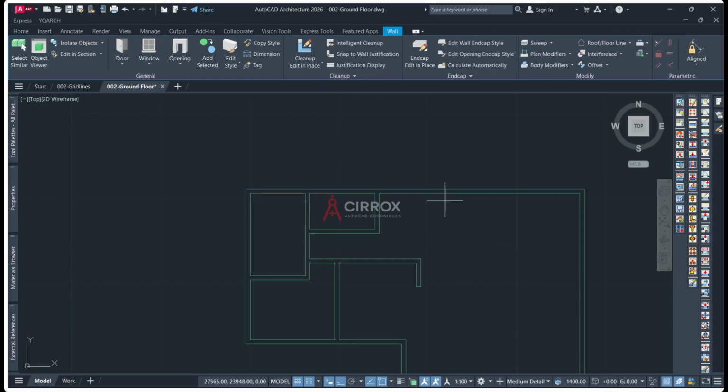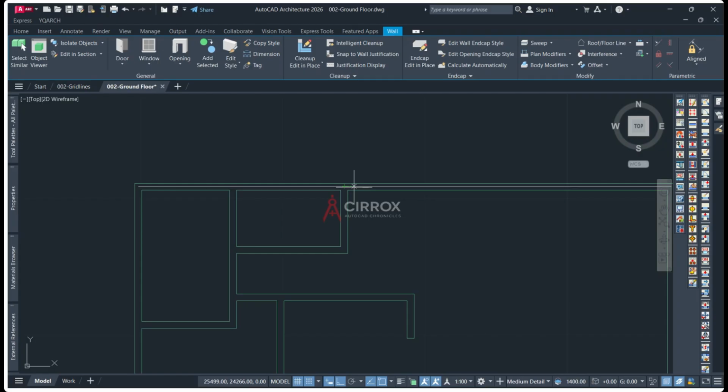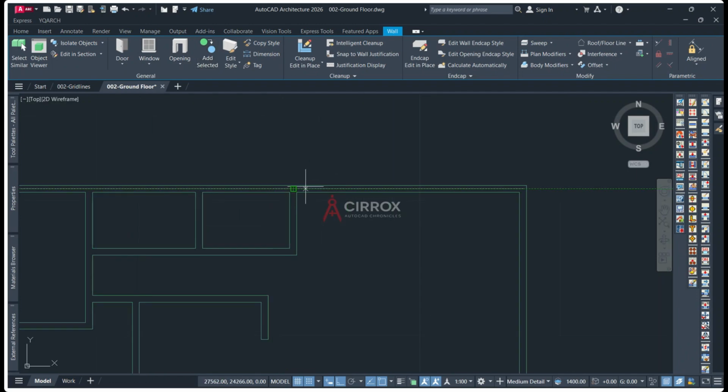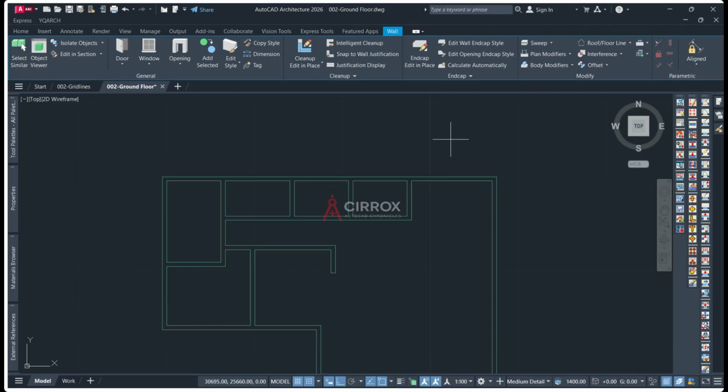I'm also going to draw another wall. Start from here, drag, give some 2,000. Now I'll also go back here and join it to this wall. So join, and selected, another distance of 2,000, drag 2,000, and then also join it to this wall, and click. So both my bathrooms have been created. Okay, so now I think I can go on with the rest.